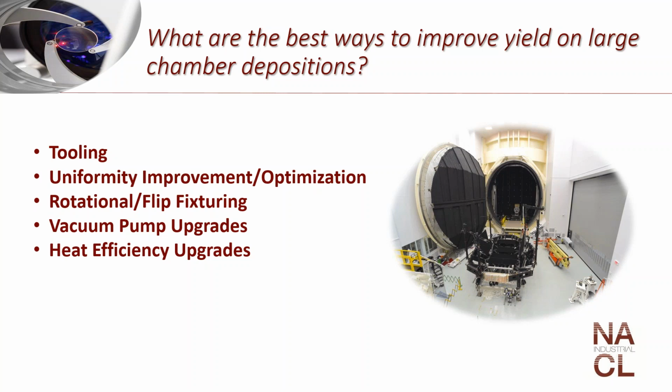So this is a pretty sophisticated way to tool things, but again, it helps maximize your throughput. You're only pumping your chamber down one time, and you're only evaporating your coating one time. You're actuating your beam one time. So again, it helps with throughput.